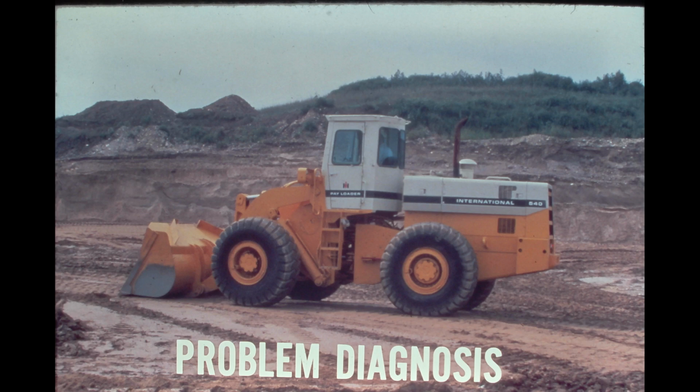The hydraulic system can be divided into 4 areas. The 4 areas are suction, system, circuit, and return. After limiting the possible faulty components to one of the 4 areas, the service person should take pressure checks and flow readings as necessary to determine which component is at fault. We'll take a look at each of these areas and the related problems.